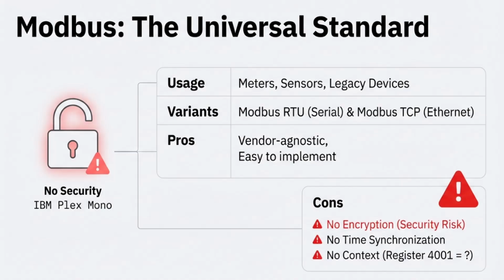In that, Modbus technology has been implemented, but the problem here is that there is no time stamping. If we don't have any time stamping, we cannot analyze the data. If we want to know at which time a specific data was captured, the timestamp within the packet is not present. Because of that, there are limitations to analyze that data and do the data modeling out of those details, right? That was one limitation, and the second limitation was no encryption.